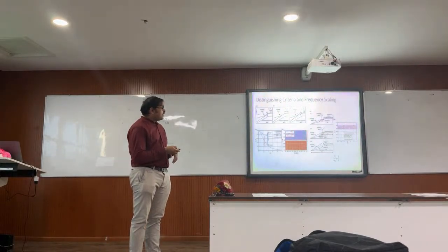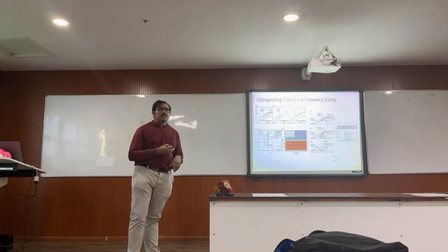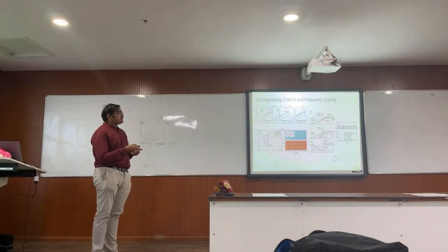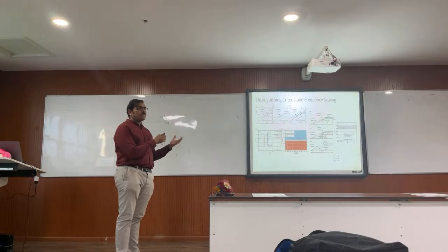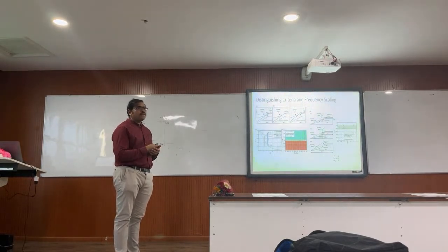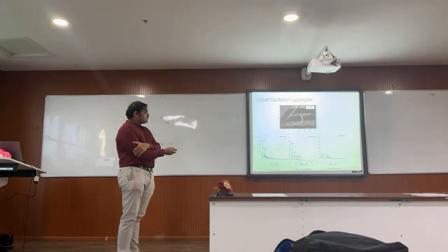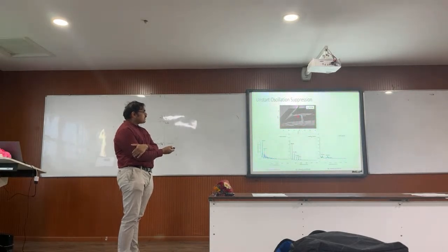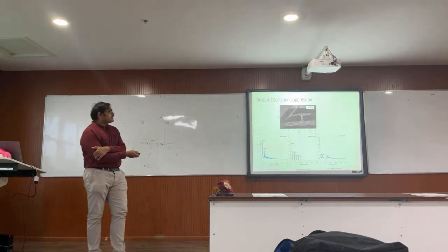We were able to collapse not only our data but several other data from before. So this is very important information, and we can also use it like a design criterion, to see that our intake doesn't fall into a large amplitude oscillating domain, and how we should look at shocks and where they impinge on the top. We are also looking at how to suppress these oscillations, and we are now looking at something called a bypass bleed, where we have a bleed which takes out the flow from the main intake, but we also have an auxiliary intake which takes it out during the unstart, and we have seen that the oscillations get suppressed here. So this is the current work that we are doing.